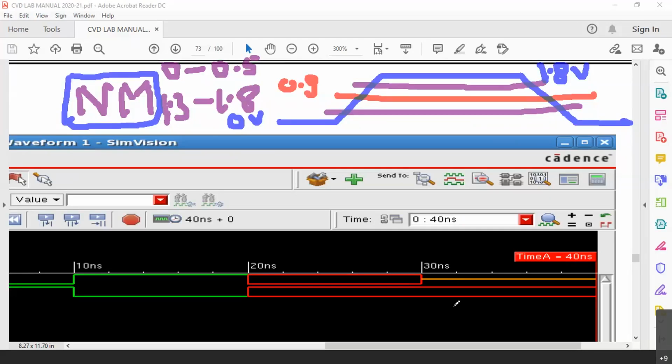So the tool has not yet completed the synthesis, hardware is not yet available, and the tool will not bother much. If the input is 0.9, the output need not be 0.9 in the case of our inverter. It can be slightly above or slightly below 0.9, depending upon the behavior of those standard cells.